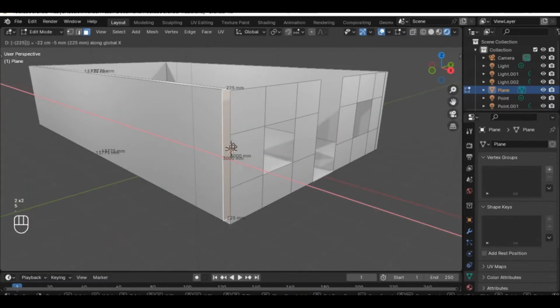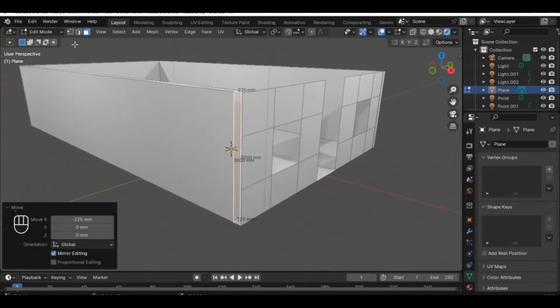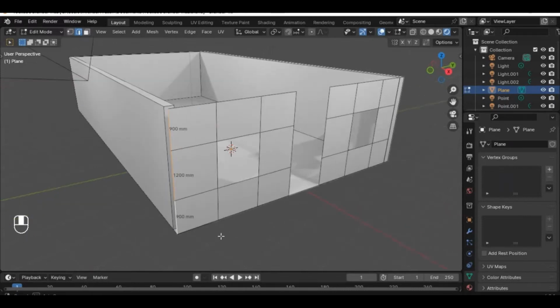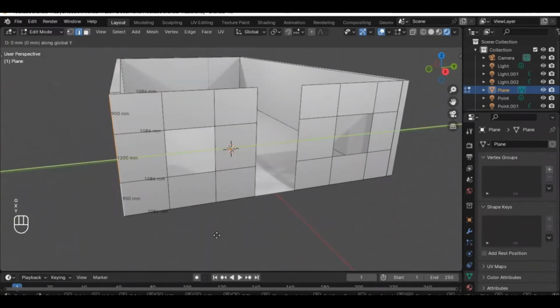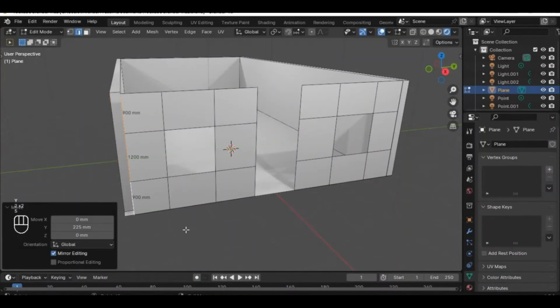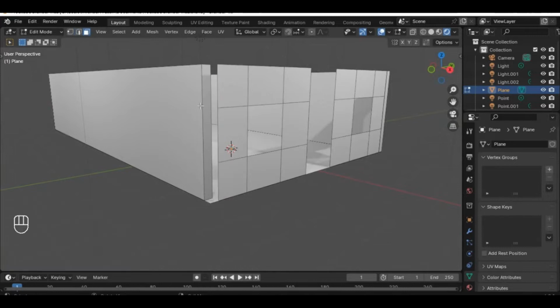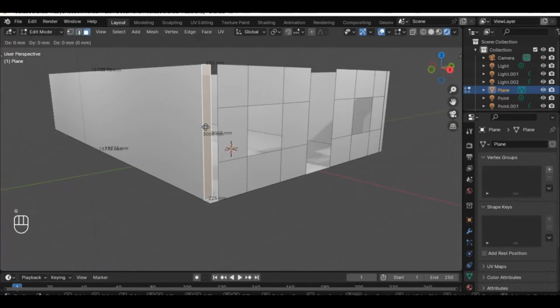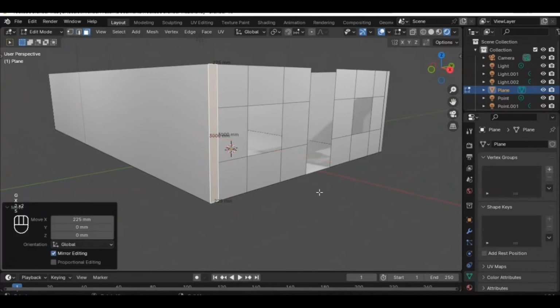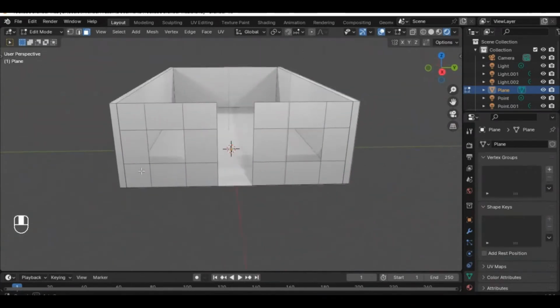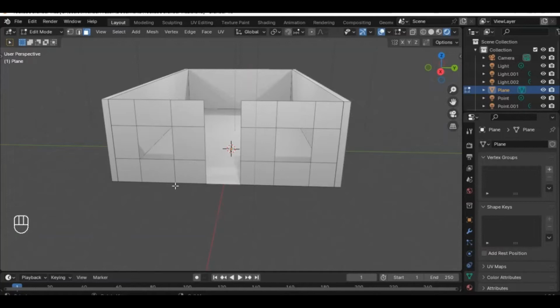So now you have your free edge to work on, so that it's now easier for you to select this edge. You can hold down your Shift and select your edges and then move it back, G Y 2.5. Then you have almost what we did here too. Then you go back to your face, then you bring this back G X 2.5 to where it belongs, and then you have what you had before. I undid what I did already.